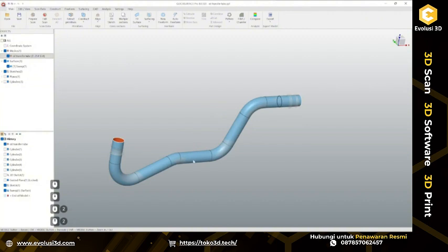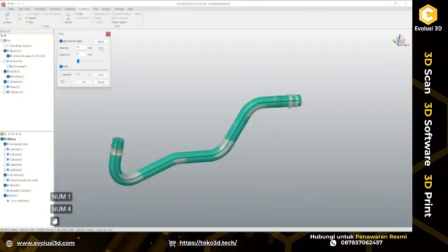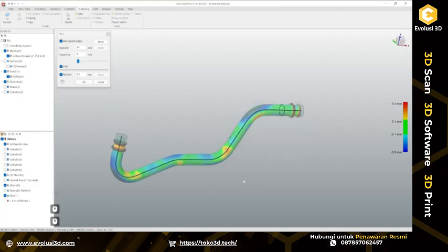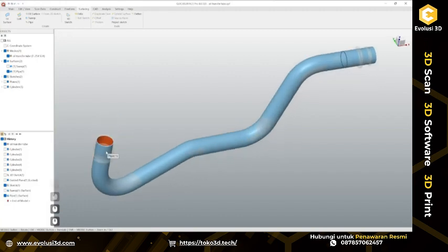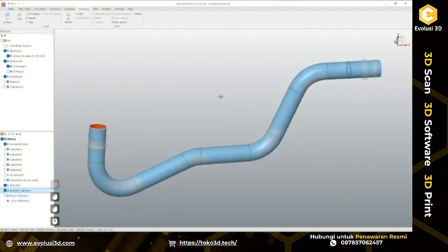So this is another way how we can achieve a similar result. And actually the third way, probably that can be used quite often for regular tubes that are bent. So we have created this path, and simply we can create a pipe across this path. We can set the desired diameter of this pipe and so on. Basically here we can set this to be just a surface, clip, and pretty much the same result, but we don't have to create any cross sections, to create planes to define these cross sections. So probably in some cases this might be way easier. So let's go back to our sweep.